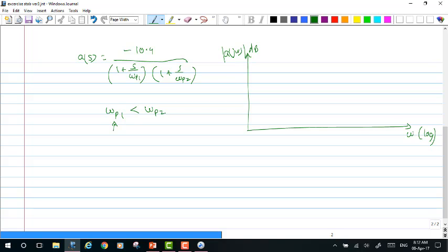And the DC gain, when we convert this quantity, would return as something like 20.34 dB as its DC gain, okay? Now we have a pole somewhere around 250 mega radians per second, and we have the second pole happening somewhere around 7.3 giga radians per second.